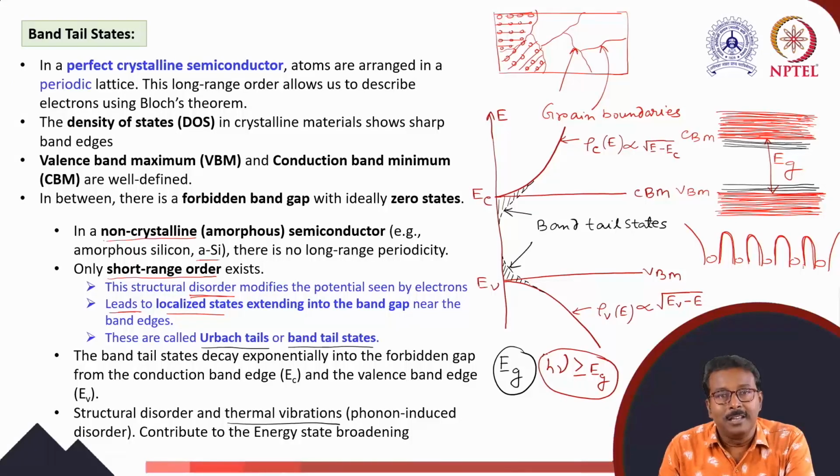That means in case of semiconductor material there is a sharp drop of absorption spectra at lambda c, a maximum wavelength, but that wavelength is now extended beyond lambda c in case of amorphous material. So that is a tail in absorption spectra, and that tail is also called the Urbach tail.